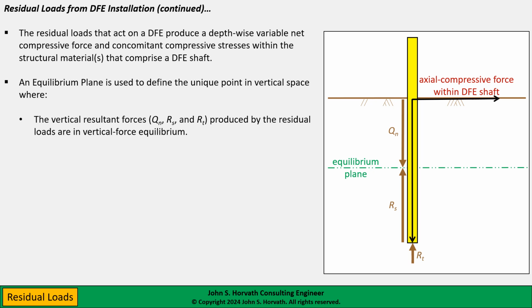So again, in a nutshell, this is residual loads. You have forces between the DFE and the ground after installation, even though no load has been applied to the head of the DFE. And again, although we're focusing on axial loads, I will show you that in certain situations, if you had horizontal or moment loading applied to the head of a DFE, these residual loads can be important as well.